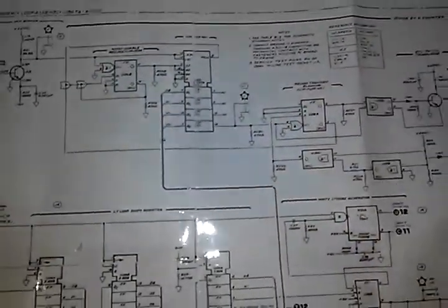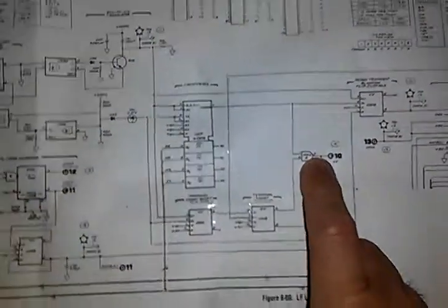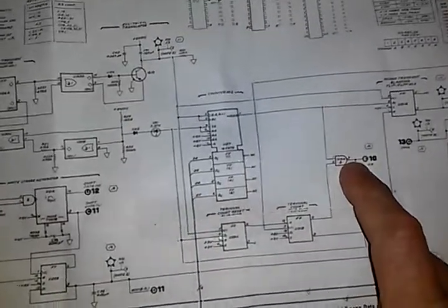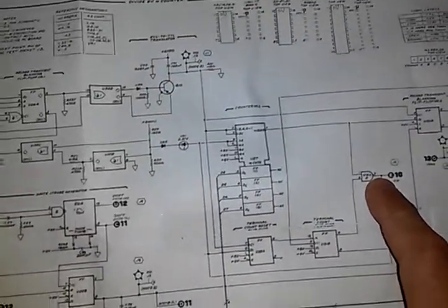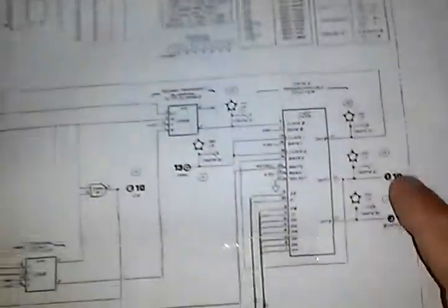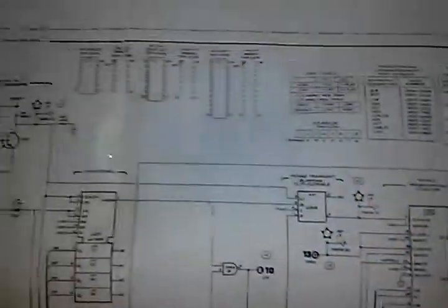Basically, this entire circuit counts to a certain level, and then it puts out a pulse here. This pulse will be a 100 hertz pulse, and that is then compared to this time base, which is derived from this 1 megahertz signal here, which is a divided signal from the 10 megahertz. I think it's 10 megahertz, if I'm not mistaken. I'm almost positive.